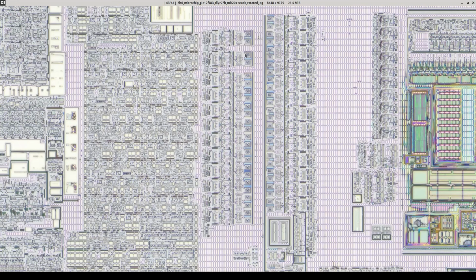And we have one column of 12 copies of this bit cell structure and one of 13. These are almost certainly the configuration register, which is commonly referred to as fuses, but these are not actually OTP. They can be wiped and reprogrammed as many times as you want. And so for a little bit of background, in modern devices, typically you don't have a dedicated configuration mode register